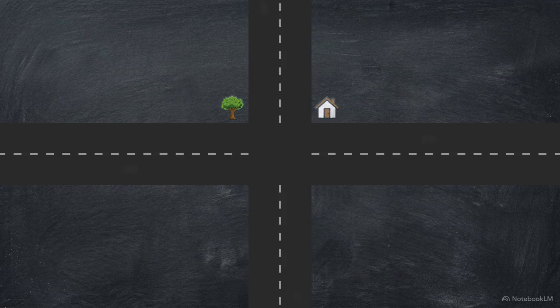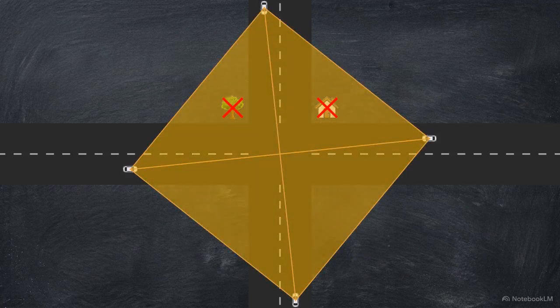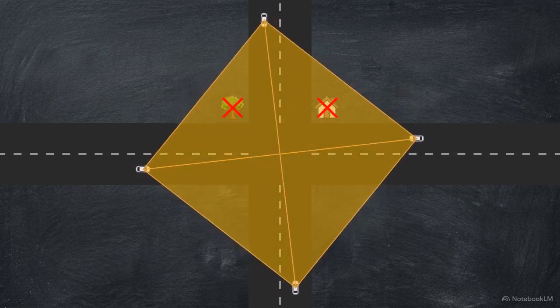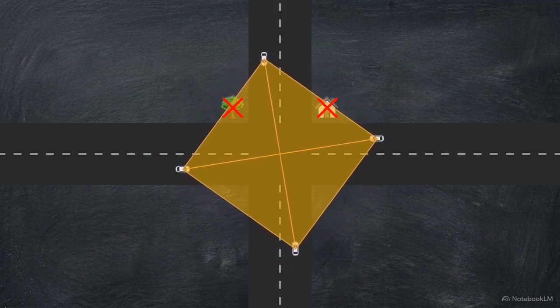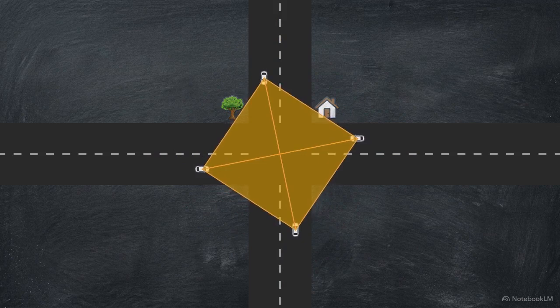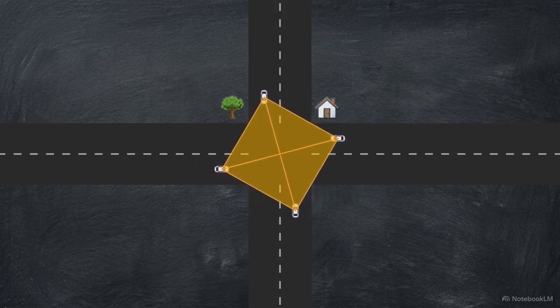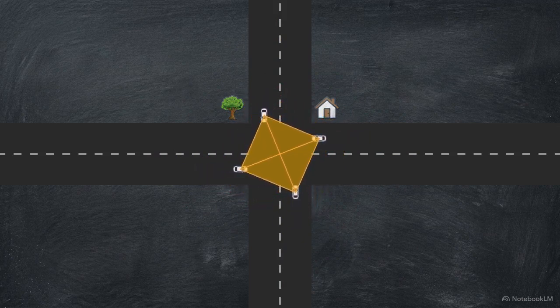These visibility rules also apply to junctions through intersection sight distance. Approaching cross-traffic requires clear lines of sight, meaning engineers must map out and enforce strict sight triangles across the corners of the junction, completely free from buildings or tall vegetation.